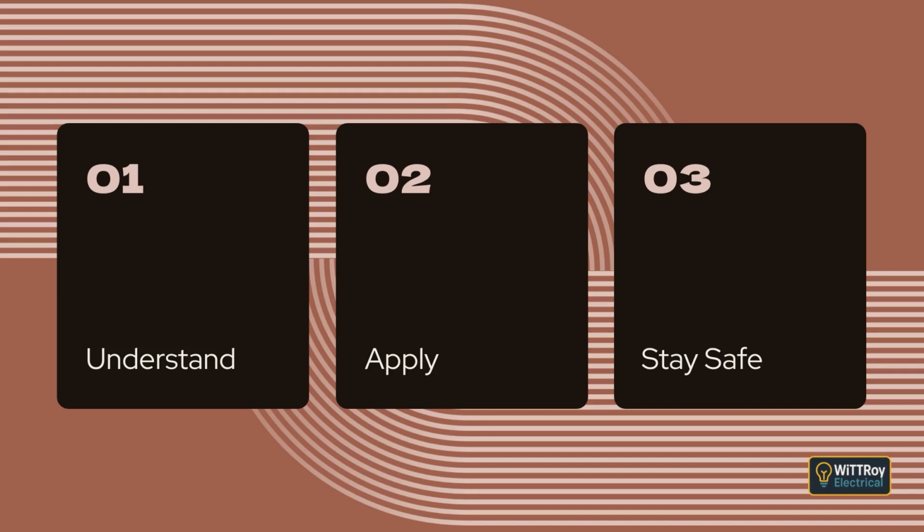Clause 2.6.3.2.2 explains that in New Zealand, certain areas used for children must have extra protection using a 10 mA RCD. These areas include kindergartens, daycare centres for preschool children, schools for children up to around year 8. There are exceptions. For example, socket outlets mounted higher than 1.8 meters. Outlets used only for clearly marked equipment such as IT gear or cleaning equipment. Outlets in corridors, halls, gymnasiums or similar places where children are unlikely to use portable appliances. Places where other methods of protection exist, such as separated supply.